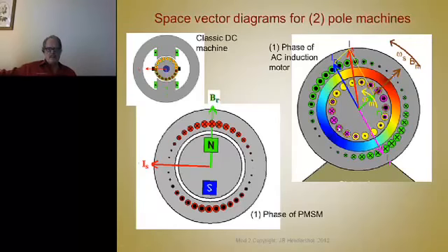And the rotor current is flowing into these bars and out these bars, you see? And those are 90 degrees approximately, not exactly. See, this is not 90 degrees. But normally it's 90 degrees. In synchronous machines, the current is 90 degrees to the B field, but in an induction motor, it's a little less because of the slip.